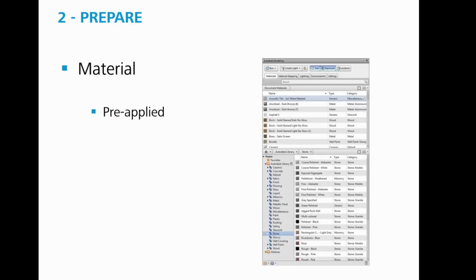And the same goes for the render mode, which you should set to full render. Shaded gives you a general idea of what the colors might look like, but in terms of actually applying the textures, so whether you have some gravel that's a bit more coarse, or some brickwork, or some in situ concrete, things like that, you want to see them inside of Navisworks.